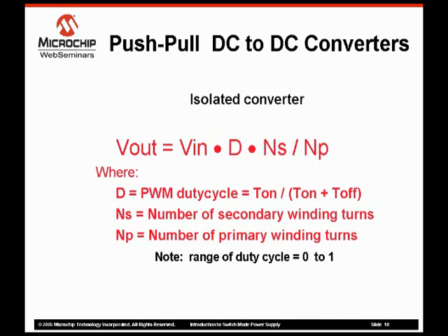The transformer turns ratio also enables the designer to optimize power efficiency in MOSFET-based applications by maximizing the duty cycle and minimizing the I2R losses. 3. The transformer provides isolation between the input and output terminals. The isolation permits output polarity independence of the input terminals. And 4. The transformer isolation capability can provide safety isolation between low voltage user accessible circuitry and high voltage circuitry.